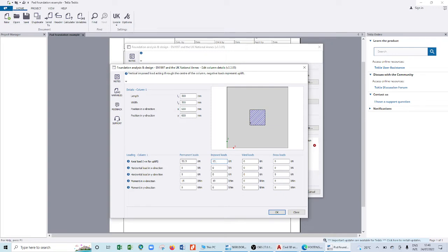For our case, we don't have horizontal load because we took a building at a height of 3 meters. If it is at a height of 3 meters, we said the impact of wind load, that's what you find on your design when it was running, wind was neglected. It starts to be experienced at around 4 or 5 floors and above. That's when it is too intense, while down at 3 or 6 meters, the values are too small, so it's negligible. So the horizontal loads are 0, 0.